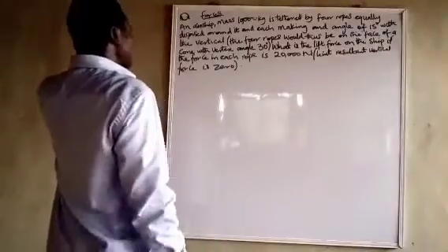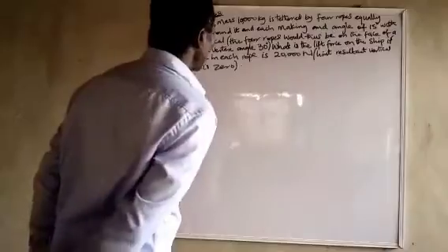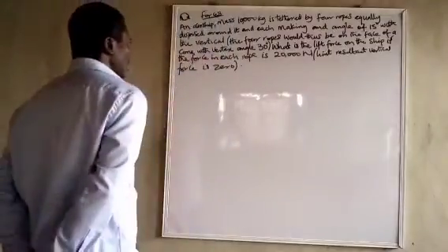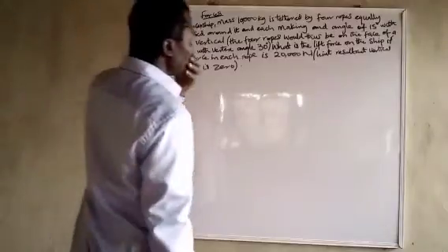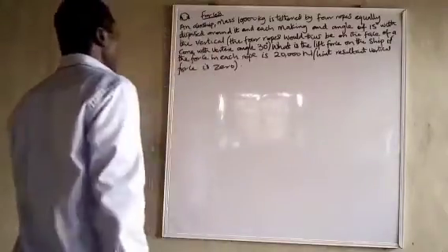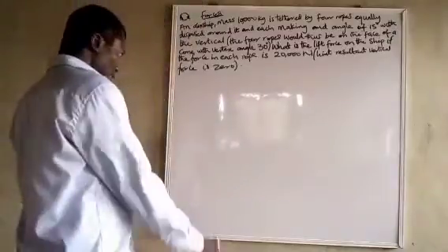An airship of mass 10,000 kg is tethered by 4 ropes equally disposed around it, each making an angle of 15 degrees with the vertical. The 4 ropes will thus be on the face of a cone with vertex angle 30 degrees. What is the lift force on the ship if the force in each rope is 20,000 Newton? Hint: the resultant vertical force is 0.